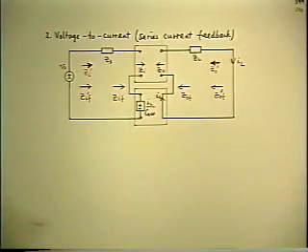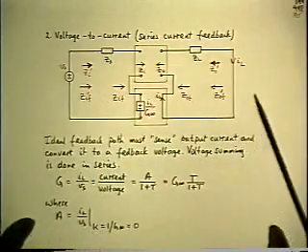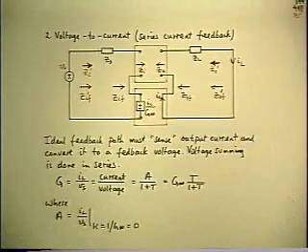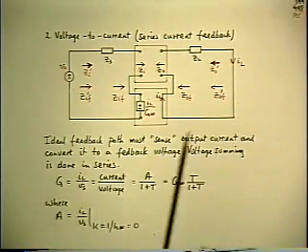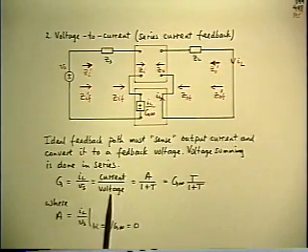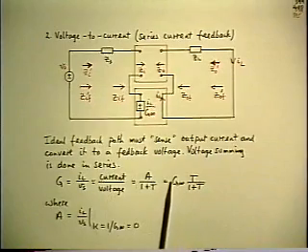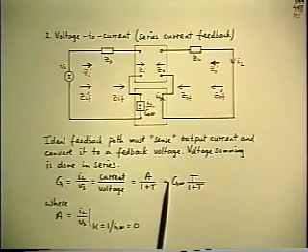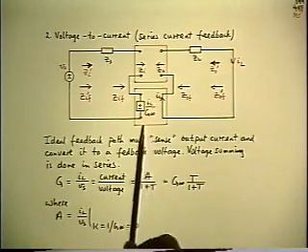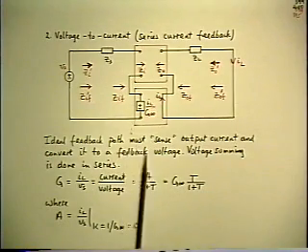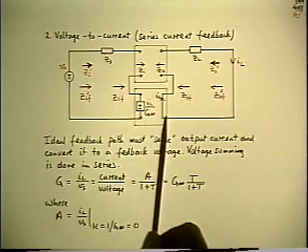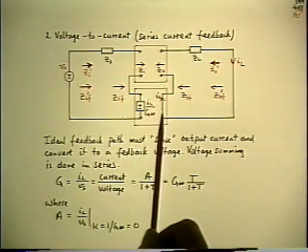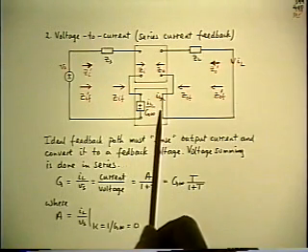And the necessary configuration this time is you have to connect the feedback path in a different way. Because now G becomes a transadmittance. It's the output current divided by the input voltage, so G infinity has to have the same dimensions. So the K box has to have the reciprocal dimensions. So the K box is now a voltage over a current, which means the input signal to the K box has to be a current.